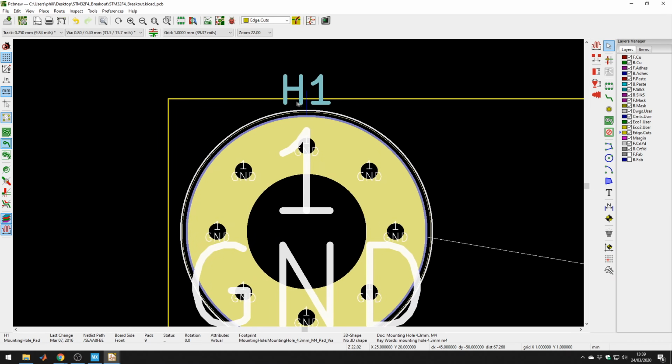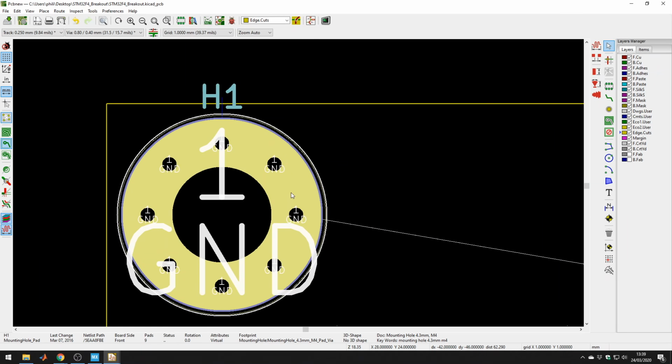You don't want to mount pads directly at the edge. The board manufacturer will have specifications or design guidelines of what distances and minimum distances you need, but this seems about safe.